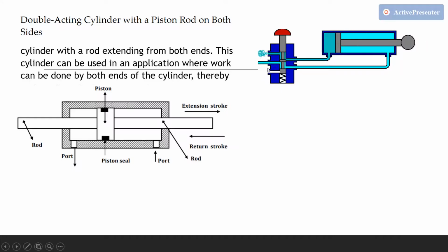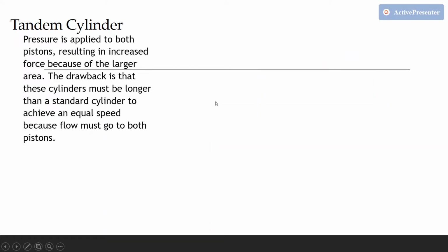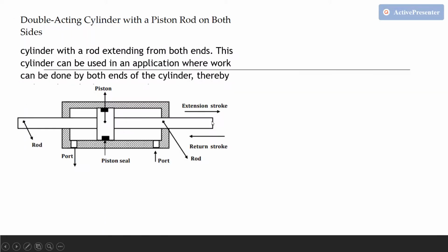So this is the port you have, the piston port and the extended rod port. Here we are giving the supply as an inlet to the rod end, so the cylinder's piston rod extends, while the other end is connected to the reservoir tank. It is a continuous closed loop cycle that performs your extension and retraction operation.